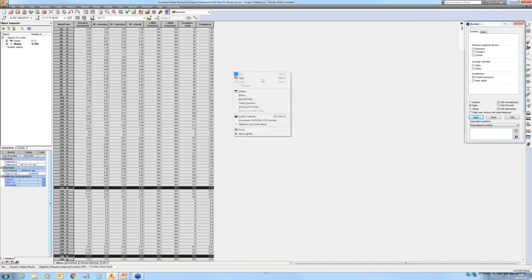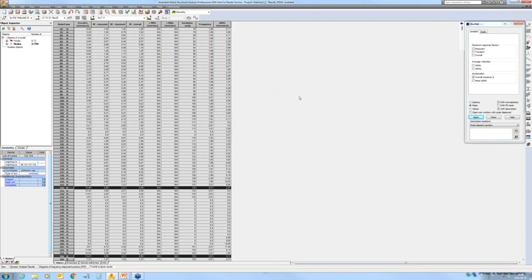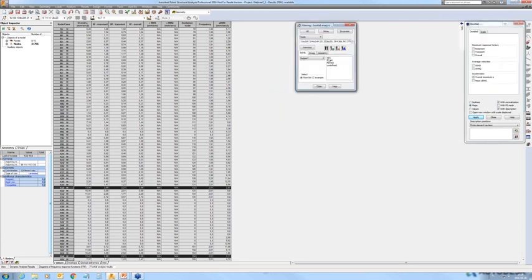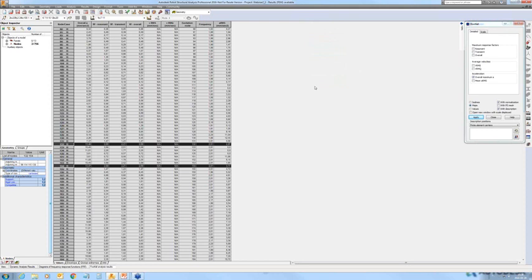Okay, we can go to table columns and we may select or uncheck certain columns. And of course, we have also the table. The table includes at the moment supported nodes, so we can go to the selection and use the selection dialog to just remove all the supported nodes, as the results in the supports are not interesting.